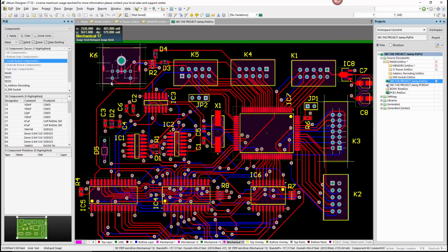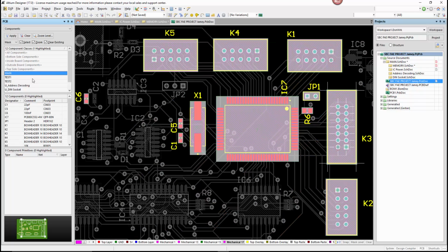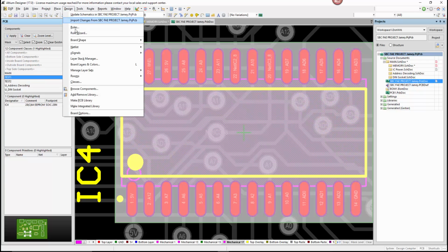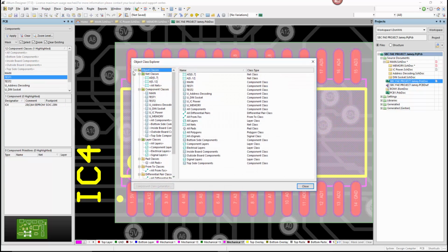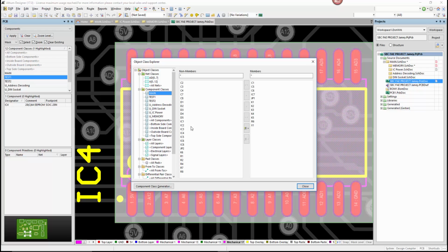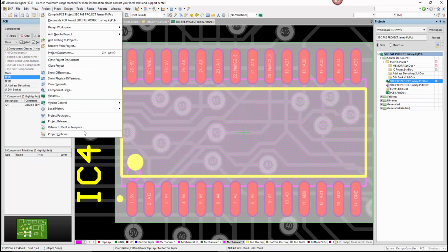We can view these classes in the PCB using the Object Class Explorer. This Class Explorer acts as a central location for all classes, but managing your class is much easier, thus saving you time. The automatic classes are those with the angle brackets. We can add, delete, or rename classes within this Class Explorer. Automatic classes can be changed in the project options under the Class Generation tab.